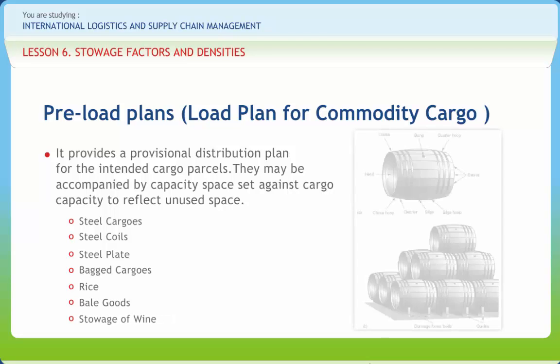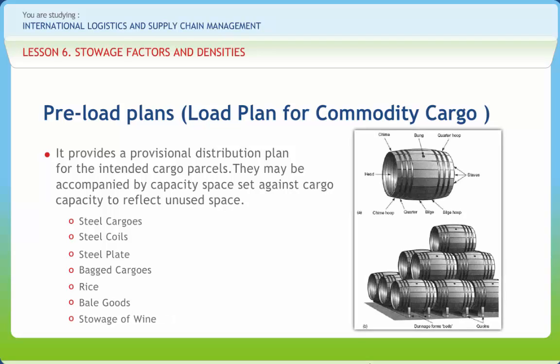The stow should not be greater than 8 high, and the first height level should be laid on a bed to keep the bilge free. Quoins, a type of wedge arrangement, are used to support the barrels and prevent them from moving. Barrels are given under-deck stowage and would not generally be taken as deck cargo.